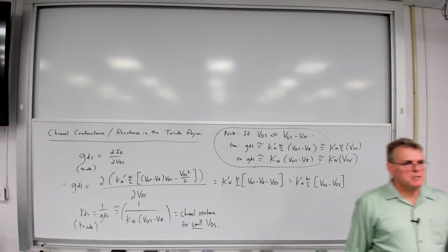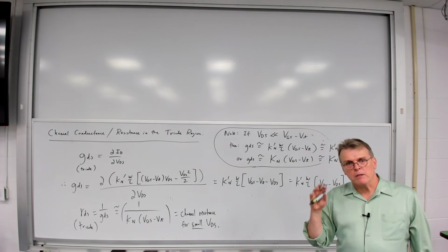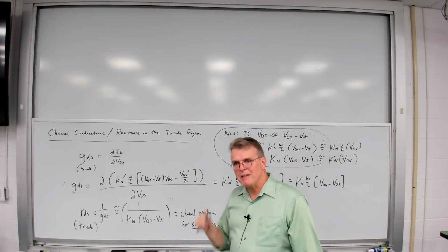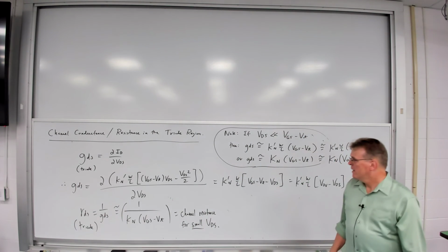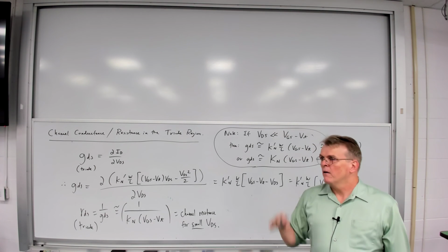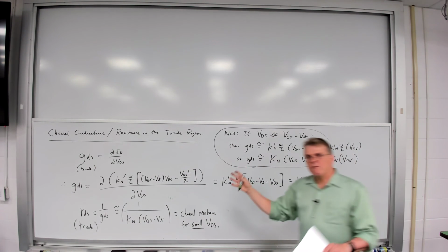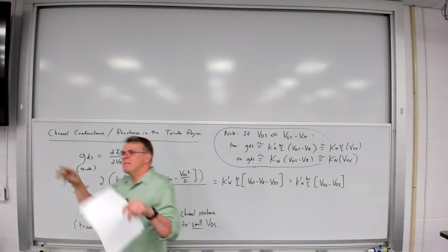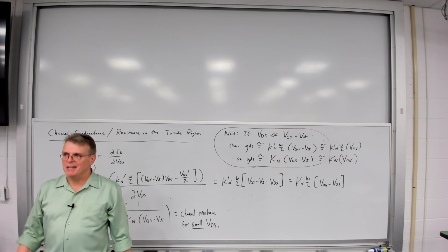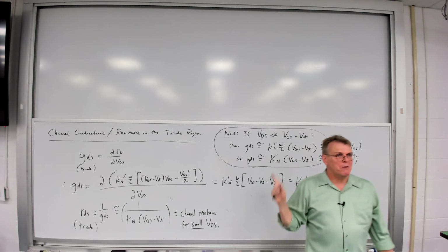We're going to see this definition again. You're going to run across this in a couple of problems. As we're going to see later on, we also have to think about what the channel resistance is going to behave like in the saturation region, but that's going to be a different problem. So, this covers all the basics for the NFET. What about the PFET? Well, next time we'll quickly do that. I'm going to sketch it. You're going to find that the PFET has the same equation forms, but the polarities of the voltages get switched around. So we'll see that next time. And then we will start working some problems with NFETs and PFETs.